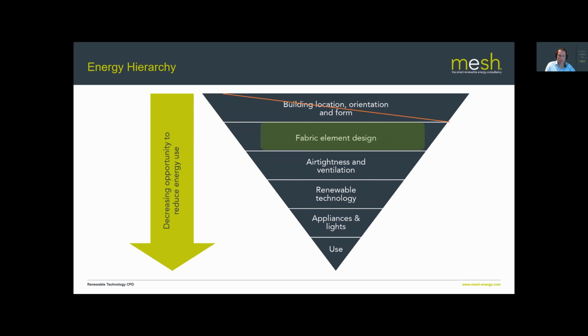It's very tempting, especially if you've got a nice view on a south-facing facade, to put loads of glass on there. But you've also got to consider how that glass is going to perform. Remember, even the very best glass, its U value is probably still 10 times as bad as a well-constructed wall. So you're going to lose an awful lot of heat through glass, even the very best glass. And of course, during the summer, large windows particularly will tend to cause overheating. So you've got to balance all the requirements quite carefully, and it takes quite a lot of thoughtful design to get that balance right.